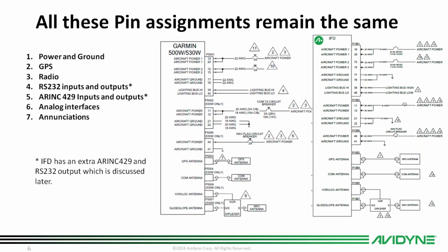Very good. That's all I have for questions here. Anybody else want? Here's one. Will the 440 work with the STEC 55X using G5? Easy peasy. Using G5, it should, because that goes through the GAD. It's no different than the EX5000. So yeah, it should work. It just has to get digitized. So it goes from IFD to the G5 or whatever the HSI is being used, and then to the STEC. So yeah, that works.